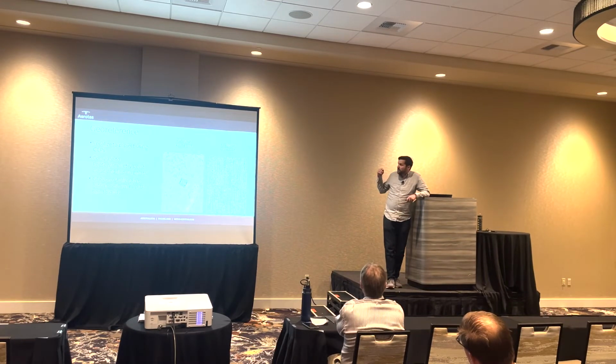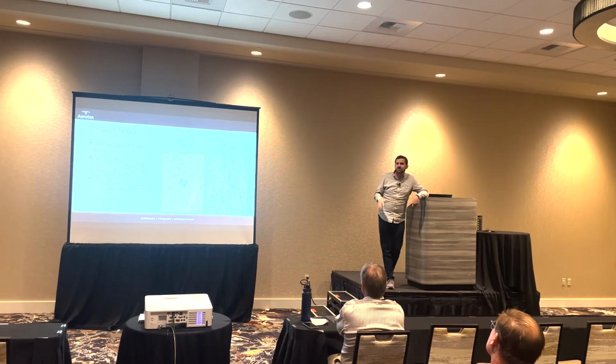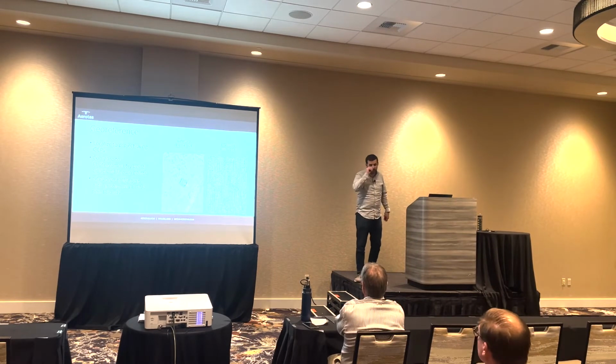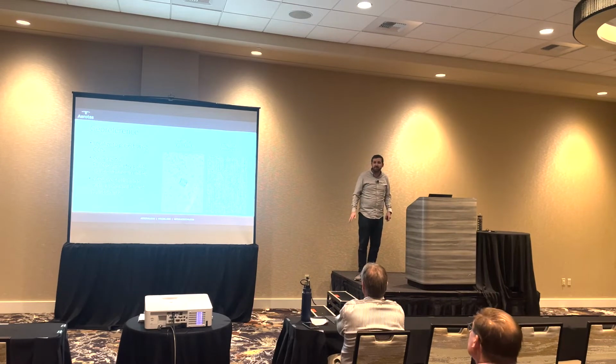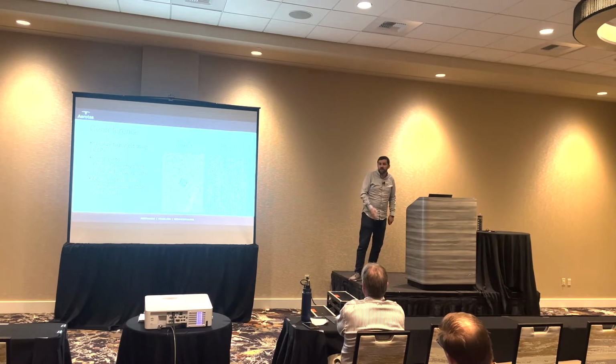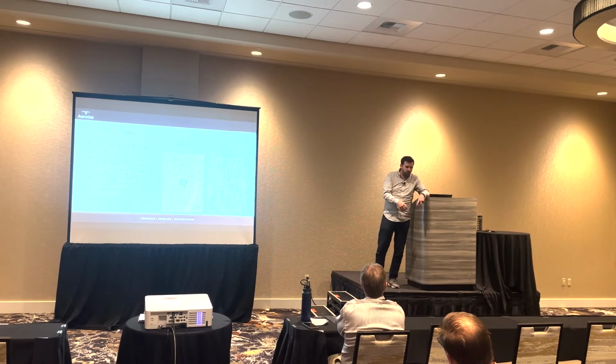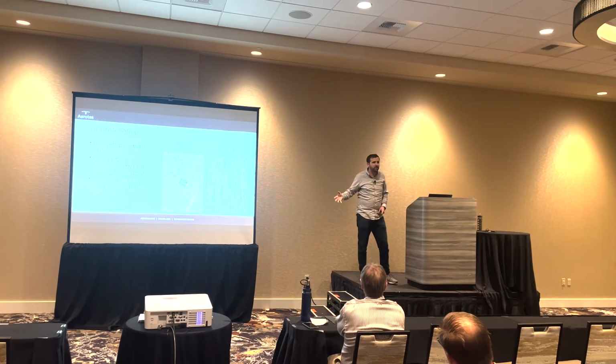Now this is important for a lot of reasons why we think that surveyors really always ought to use ground control points. A lot of hardware vendors out there will say, oh, you can do a survey without ground control points. And we actually really hate that, because if nothing else, this is a check on human error, right? If you just have blind faith in the equipment, there's no way to catch any sort of blunders, right? Anything from just you're setting up your base over a known point and you key in the decimal point in the wrong place, there's no way to catch it if you don't have ground control.